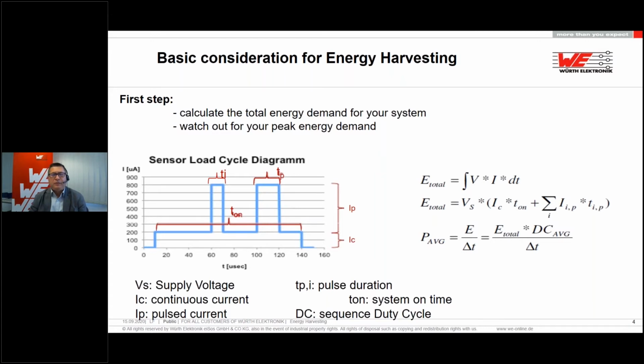You have times when there is no calculation or sensing need, and you can put the microprocessor in deep sleep mode, and you can wake up on the event, on the threshold, and then make your calculation and again put it to sleep. You can keep a deep sleep mode at very, very low leakage current, which is sometimes even less than the leakage of the internal resistance of the battery. This is very important when you develop energy harvesting devices.